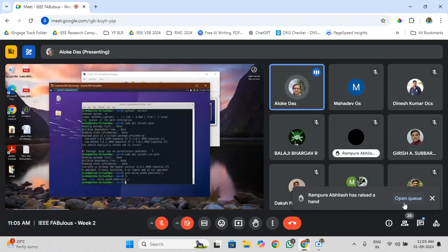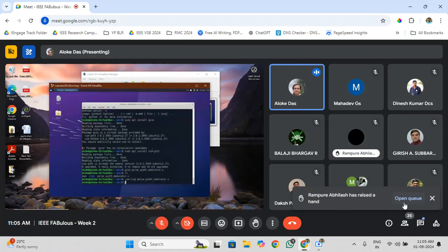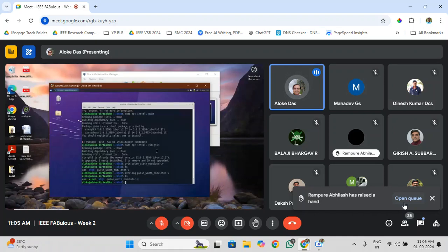So if you come out, it is there. Do ls, see the new file is there, and try to compile it with iverilog, the newly created file. So it is compiled. It's an empty thing, but it's a valid Verilog file. And when you compile a Verilog file successfully, you get this output, a.out. It was not there before. So that is a simple demo of gvim. gvim is a GUI editor where you can create your Verilog file.